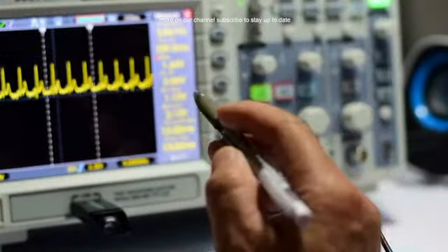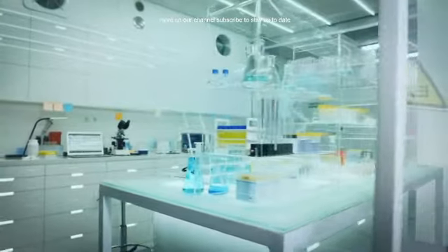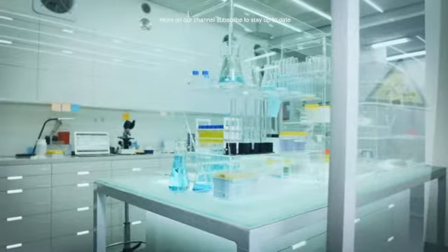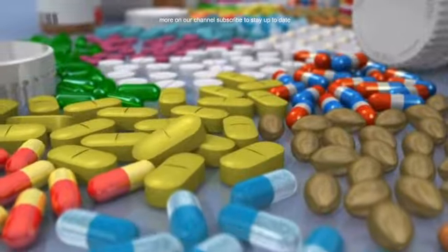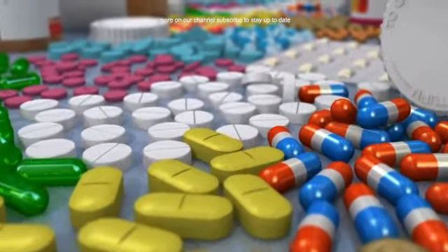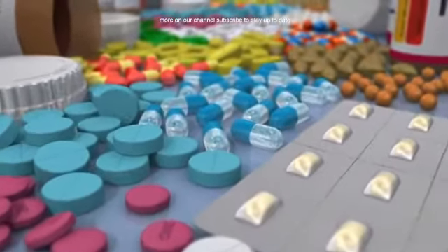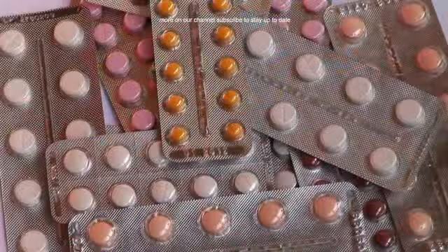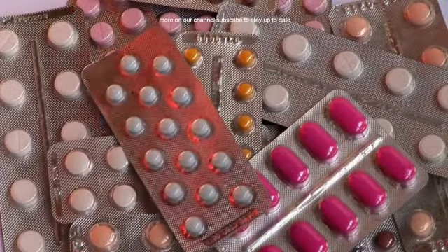Calibration of measuring, weighing, and recording equipment is essential to ensure accuracy. Scales, thermometers, pressure gauges, and analytical instruments must be calibrated at defined intervals using certified standards. For example, a tablet press requires regular preventative maintenance to ensure all parts are functioning correctly and to prevent issues like variable tablet weight or hardness.